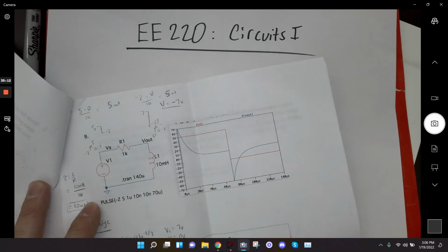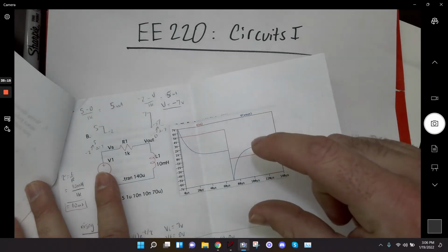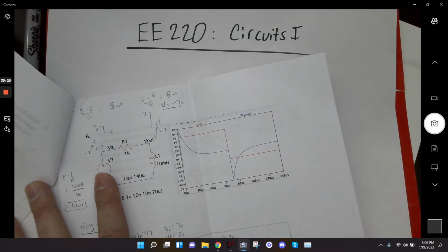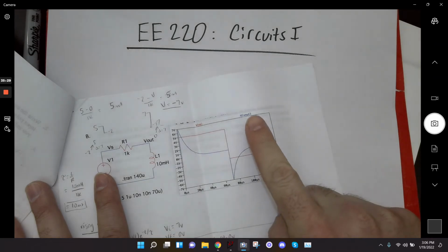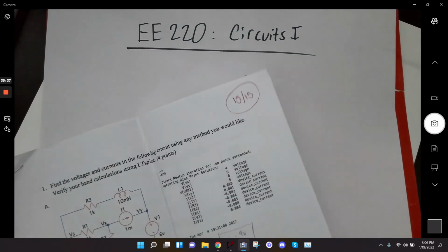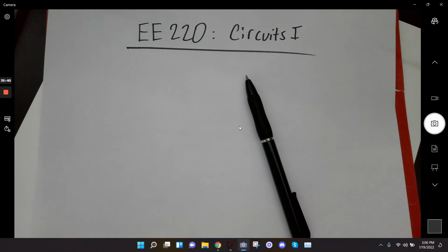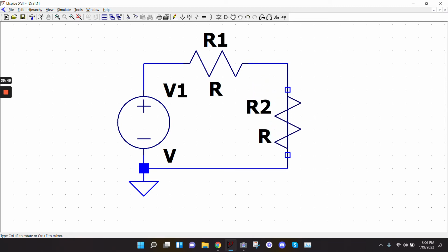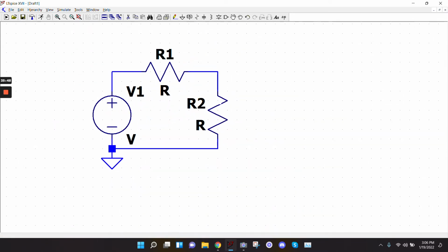Another thing you can do in LTspice when you plot things is split the panel, so it won't just be one plot with two waveforms on it. You can get two separate plots, so then I can see which waveform is which. You can plot the red one on the line above and the blue one on the line below, and since they're labeled, I'll know which one's which. So if you guys can't print in color, that's totally fine. Here, let me just show you guys how to split the plot pane real quick. You probably won't need this for a minute, but I'll do it anyways, just so you can see it and I can answer your question. Wow, that's really bad.